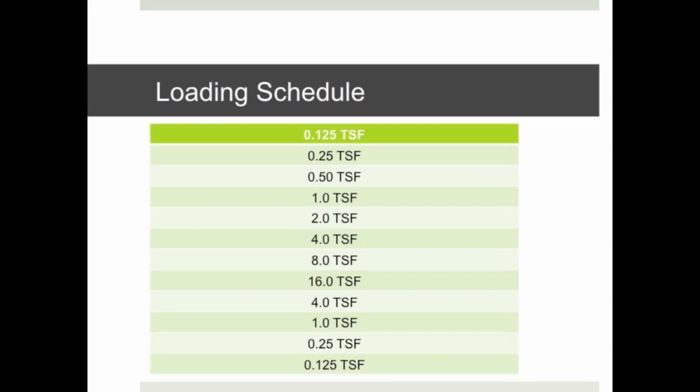The incremental loading schedule. We will apply these axial stresses onto the sample according to this regimen. The vertical deflections will be measured throughout the duration of the load. The incremental loading schedule must be predetermined so that the calibration can be performed along the same regimen.